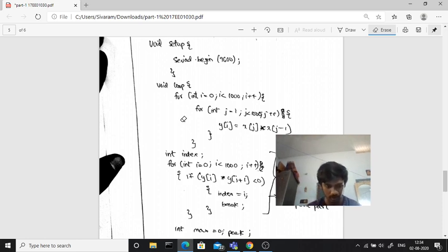The autocorrelation function is R of m equal to x of m into x of n plus m, where n is equal to 0 to N minus m minus 1. Here we are doing the same thing, which will help us to reduce the noise and make our signal smoothened. Once the band pass filter and the autocorrelation function are done, we will get a periodic type of signal, and hence we can find the time period and frequency of the signal for a small certain period of time.